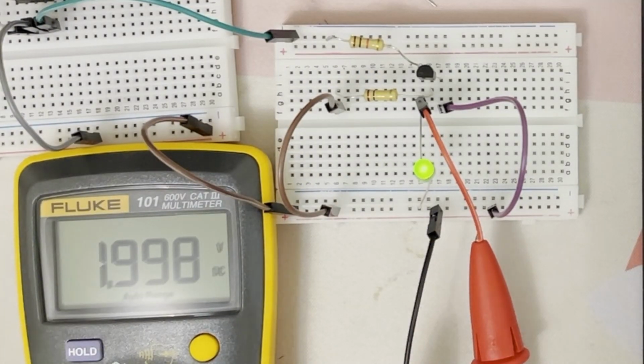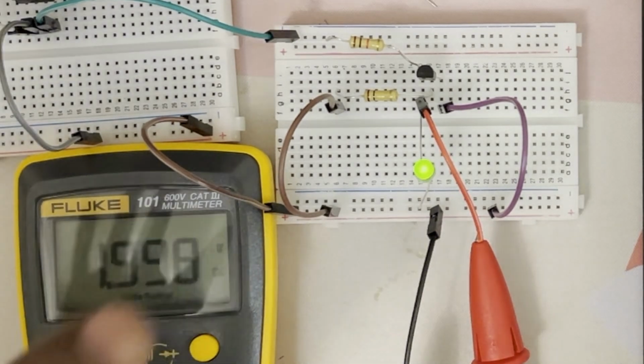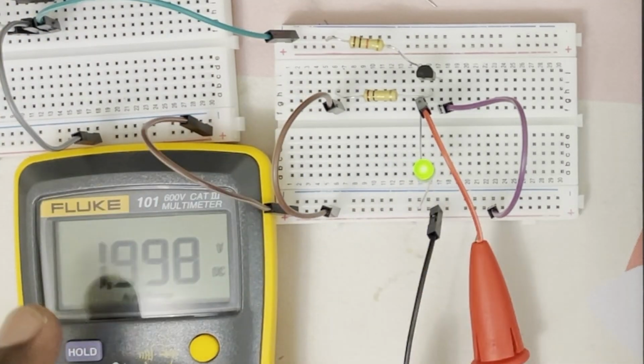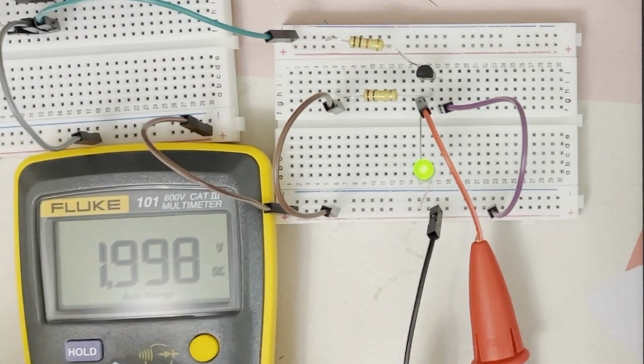Okay, now just recheck again. For this circuit, if I put A equal to 0, then the voltmeter will be 5 volt or the LED will be turned on, right? Now here you can see A is 0, LED is on, output is 2 volt. Take out the LED, it will be 5 volt, no issue. So that means A is 0, output is 1, this one is satisfied, no problem, right?